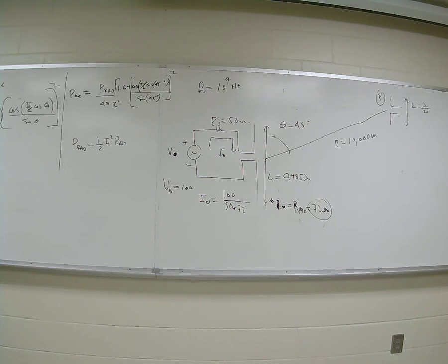So I'm not going to give you those. I'll give you the radiation resistance of the short dipole, and I always use radiation resistance to get my power radiated unless it's given. And then I use the directivity to get the power density in the E fields. I don't use the E field equation directly from the current, ever. All right? I got PAV as 2.04 times 10 to the negative 8. And that would be watts per meter squared.